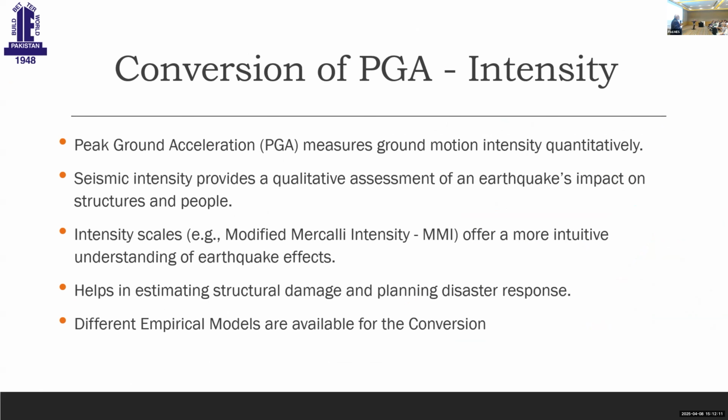I must mention here that earthquakes normally are identified by the magnitude. The magnitude is very important, but the magnitude is a constant number. Whether you have felt the earthquake or not, it was a 7.7 magnitude earthquake. But in different parts of the region, you will feel intensities differently. So the vibration felt in Yangon and the vibration felt in Mandalay are completely different. That is why we have to have the intensity mapping also, because the damage of the building is dependent on the kind of intensities the building is subjected to. And then the intensities are converted into some other things which I'm going to talk about here.